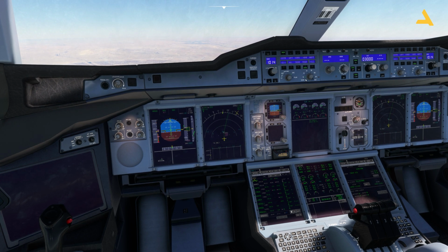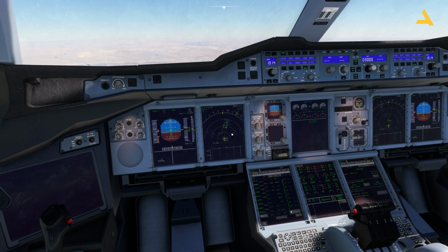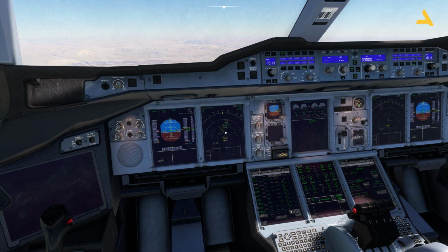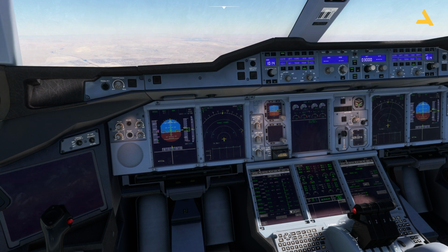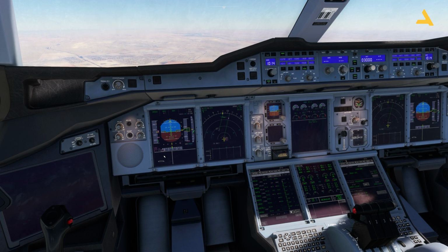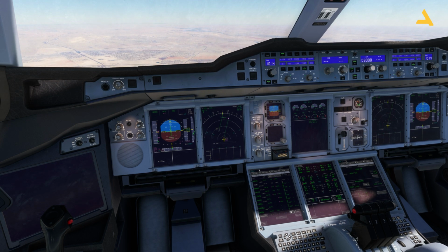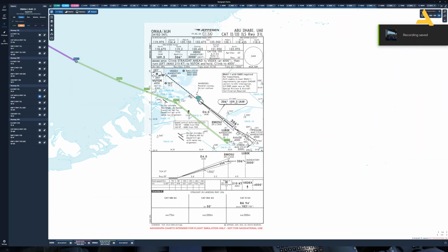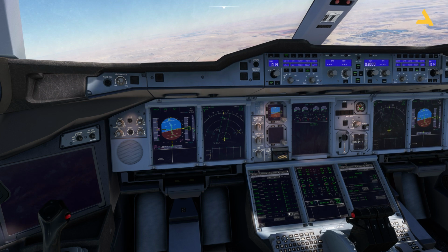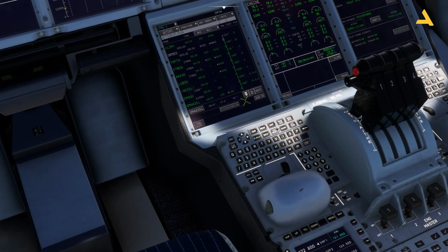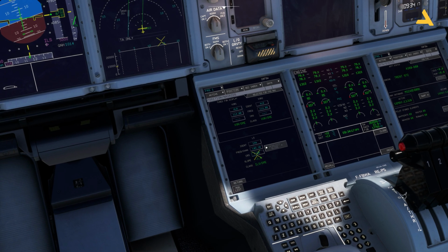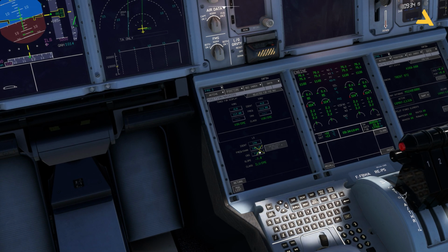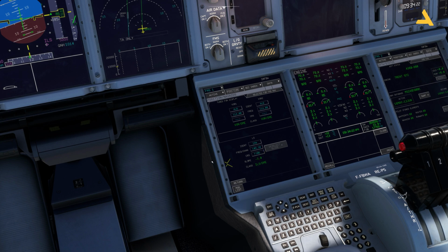Now after this point I can also activate the approach, as now there's only one turn left and I'm near the airport. Press this button LS to get this information for the ILS. If you go over here in this section, nav aids, you will also see the frequency, and the heading for the runway is also coming, 306.